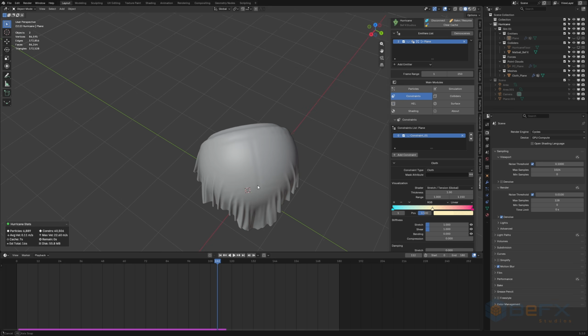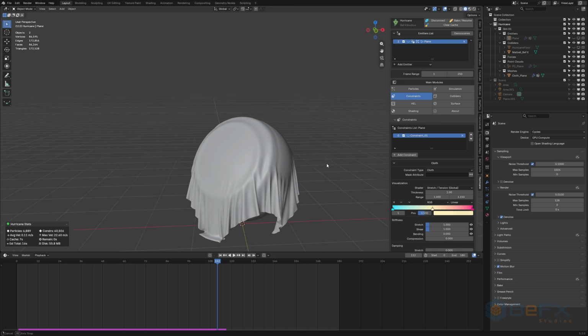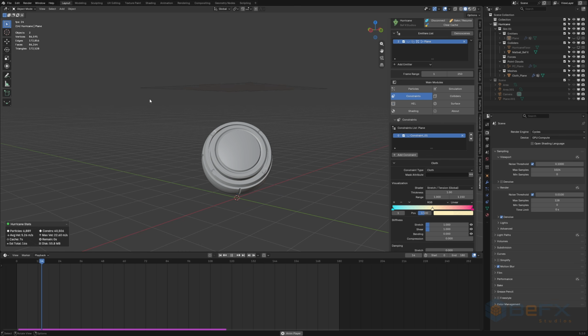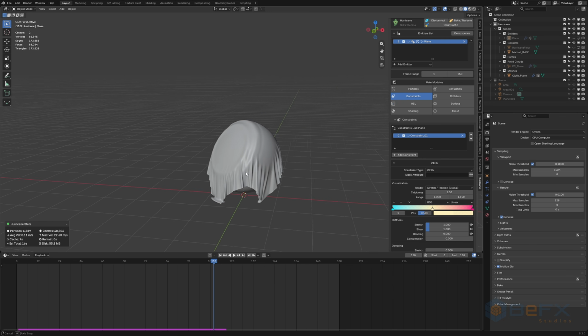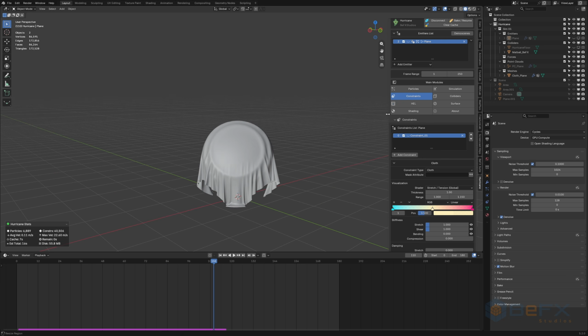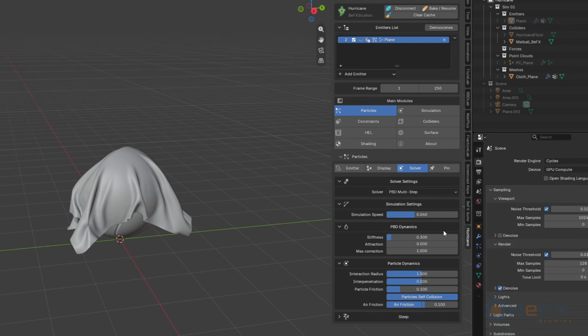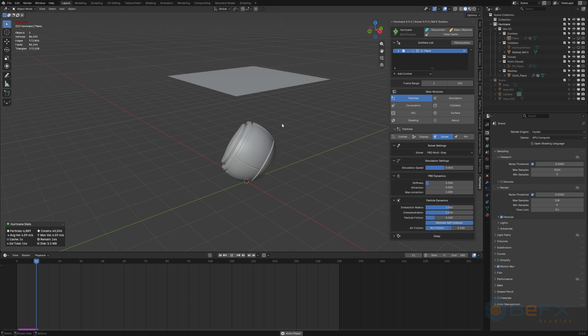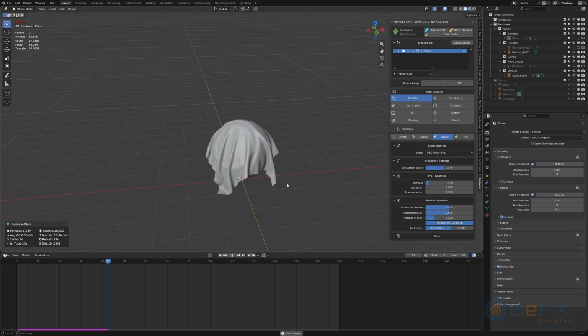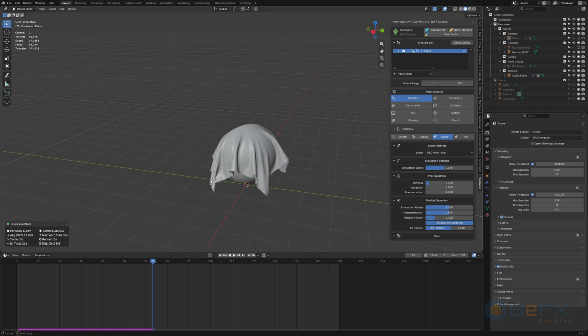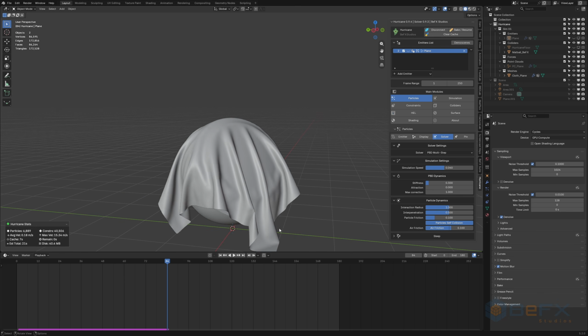Within the Constraints Visualization section, we can enable various display modes to evaluate the internal state of the constraints, analyzing parameters like tension, compression, or elongation levels across the fabric in real time. We can adjust settings like thickness or display ranges to achieve a much clearer graphical reading. This tool proves immensely useful for diagnosing cloth behavior and obtaining immediate visual feedback while tuning our constraints.